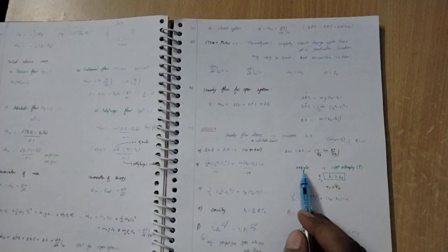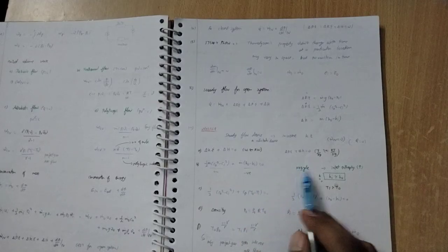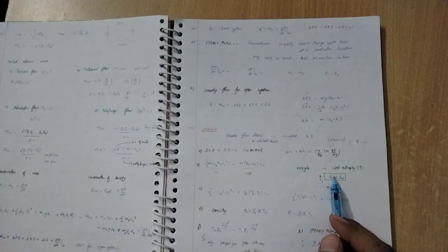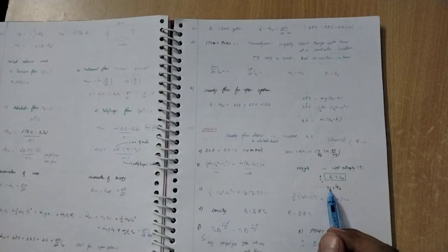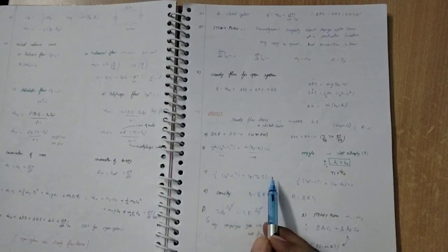Okay, this entire thing. In a nozzle, inlet enthalpy is much higher, h in greater than h out, so generally T in will be much higher than T out. These are the extra things. For density, rho out equals P out over R T out. For reversible adiabatic flow of perfect gases, we need to use perfect gas relations between T and P. Since it is steady flow, m dot in equals m dot out. This is just interrelated.